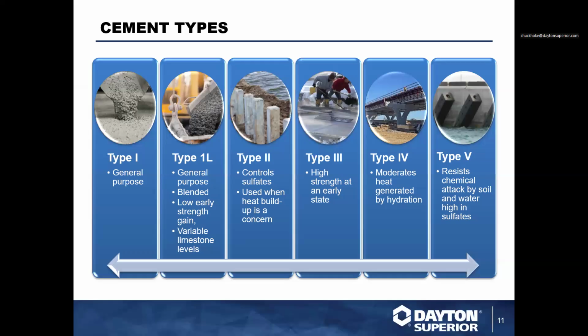And type 5 resists chemical attack by soil. Typically, you'll see that used for underpinning projects, piles, concrete caissons and piles being driven. We'll typically use a type 5 cement for that type of concrete mix.